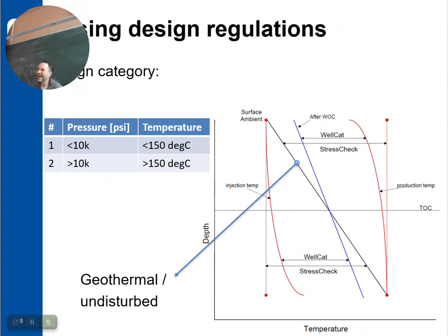That gas from the formation migrates up in your annulus, and all subsea systems have absolutely no surveillance by standard design in their B annulus. So your casing design for a subsea well has to be checked in Velcat, regardless, to find annular fluid expansion in the B annulus, right?